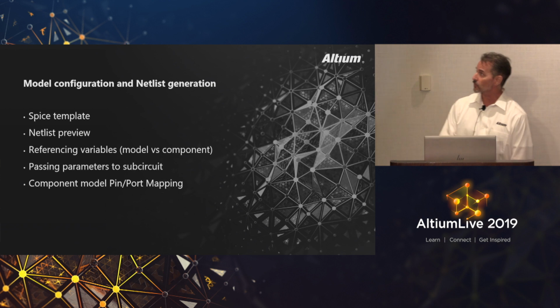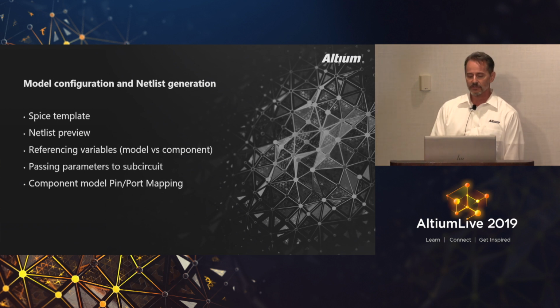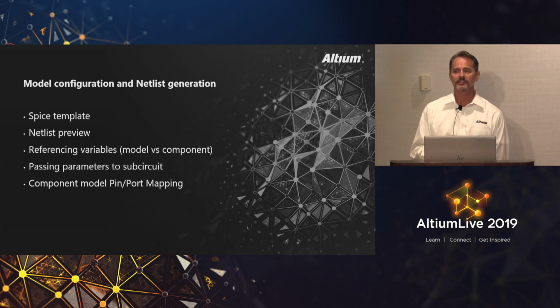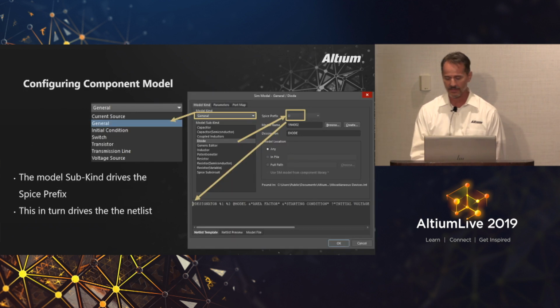Now, next we're going to look at configuring netlist generation. Of course, there are a few different pieces to that. You have your SPICE template and the preview, and especially if you're building your own components, you want to be familiar with the syntax.